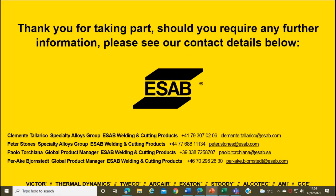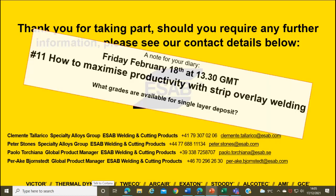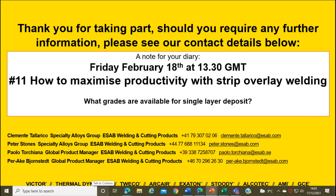Well, maybe this is the topic for the next webinar, because it might take several minutes, as there are many topics to consider. But at least the main ones are the technical specifications, because sometimes the end user is imposing the welding process to use. Then, of course, it can also be the know-how and the previous experience of the manufacturer, and the welding equipment available to the manufacturer, because, as we saw during the presentation, electroslag needs higher amperes. It means that bigger power sources need to be connected to the welding torch.